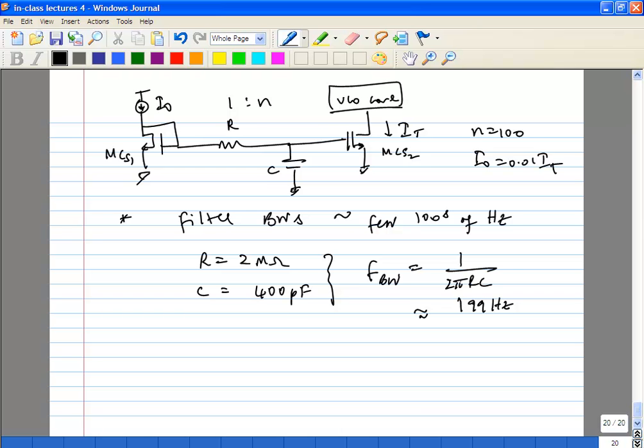I thought the basic thing is we wanted to keep the area down, right? Why would you want to use an LC there? Imagine you actually want to get a low pass filter. An LC would give you something, but to get the same low pass characteristic, you would probably need to have a much larger L. In this case, the L is series and C is shunt, so you will get a low pass response. But to get the same filter bandwidth, you need a much larger L. Okay.